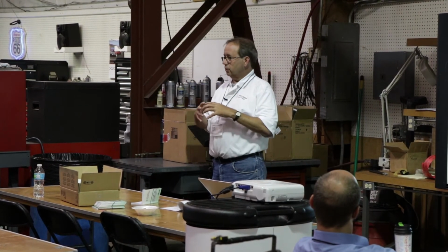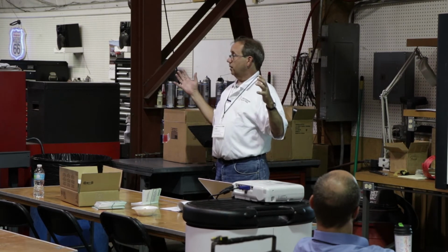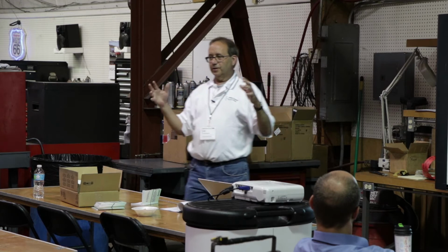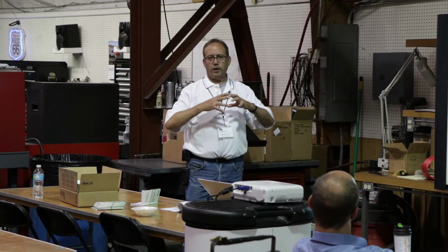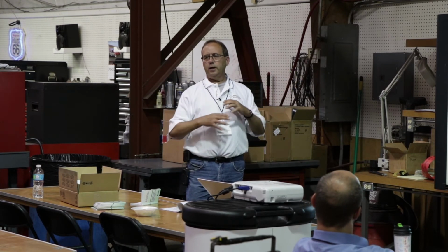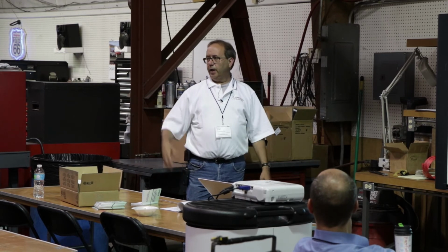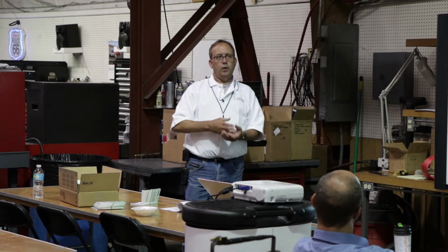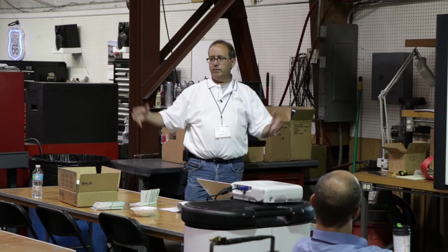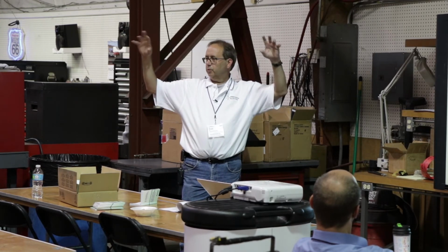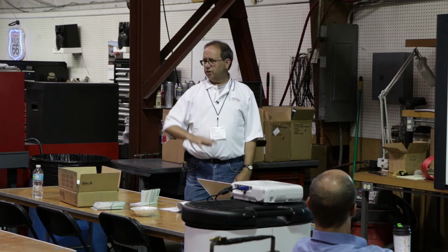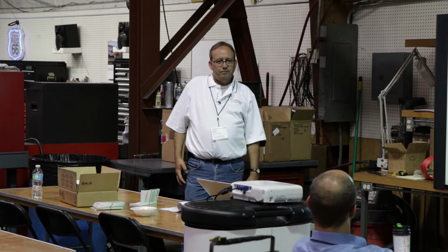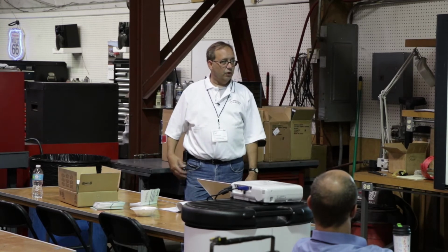Because this motor physically, we've got pictures around here someplace of it. I should dig those out because it's pretty impressive. But the comm segments came apart in it. It wiped out everything. And the mica that's in between the comm segments got airborne, and it was just flaked. It looked like it was snowing in there. It was just insulation and copper everywhere, because they lost control of it.